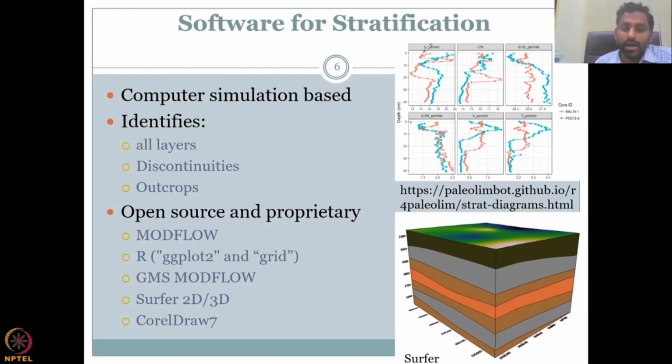So we have now seen that it is very important to have these layerings done so that we understand that the layer has to have only dominant identification points. If it is very small, the layer should not be called, for example, a clay layer, if it is only 10% clay, or it's the first clay that you see.